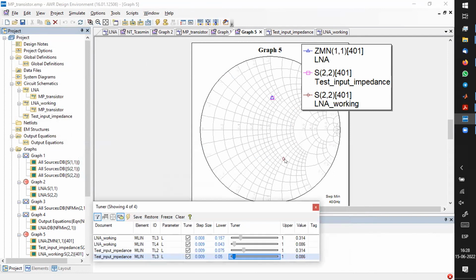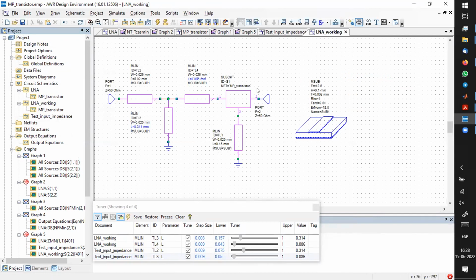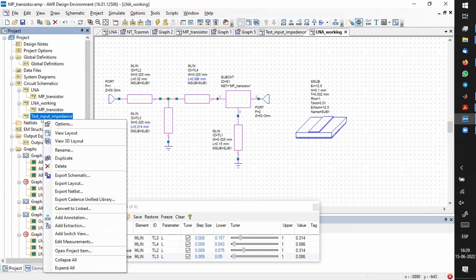This is the output of the transistor. So we are looking, you can show it maybe there, where we are looking at now. The schematic. So yes, we are looking towards that direction. And now again, you should add a matching network to get to the optimum or close to it. We do the same, we use an output impedance. I would suggest to have a piece of a series line.